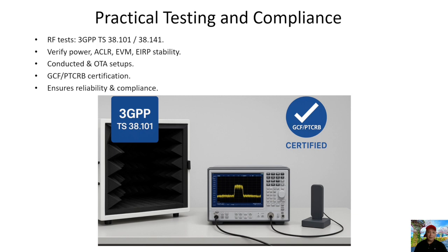Test cases verify EIRP, ACLR, EVM, and output power stability across frequency, temperature, and bandwidth. These validations ensure consistent user experience and prevent interference in real networks.